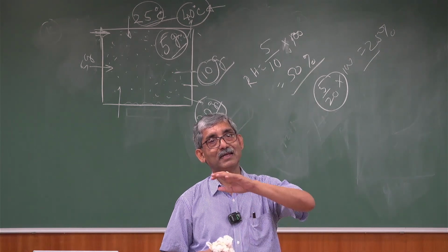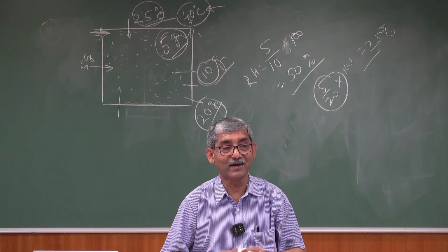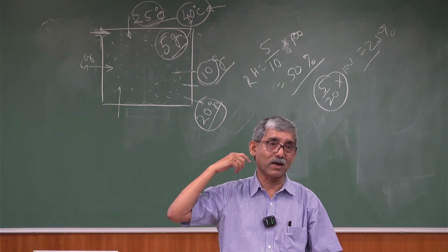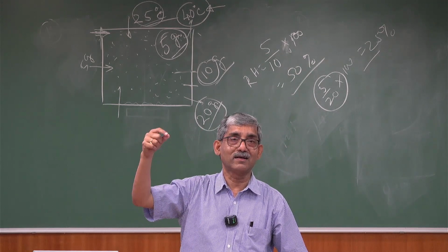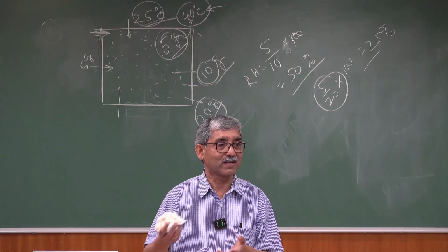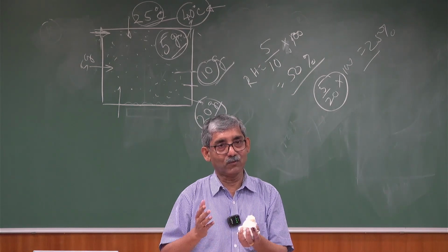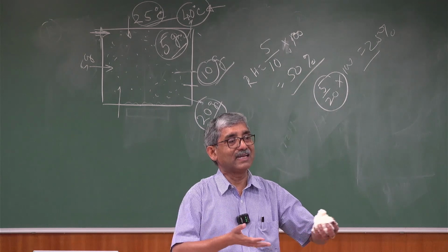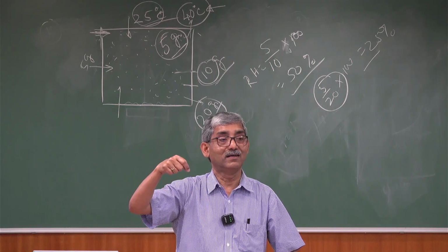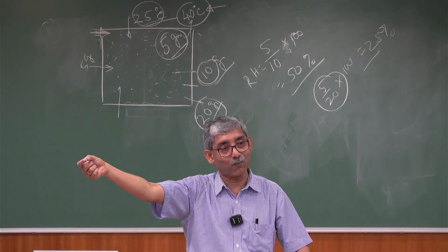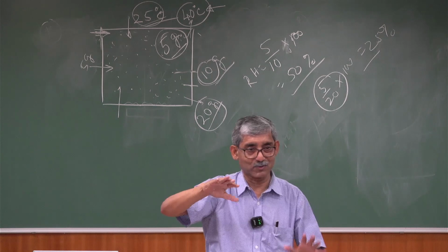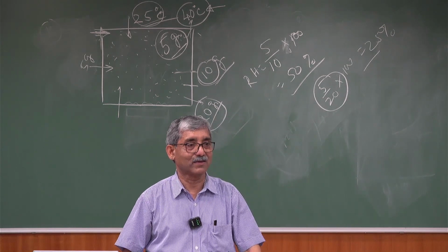That's why there is an internationally accepted regain level, and you have to correct your weight. Suppose we have produced material; the accepted standard is 8.5% relative moisture regain for cotton, and what we have produced has 10% moisture regain. So accordingly I have to correct the invoice weight to bring it to the 8.5% level. If it is dry, then I have to increase the invoice weight, so that the pricing is done correctly.